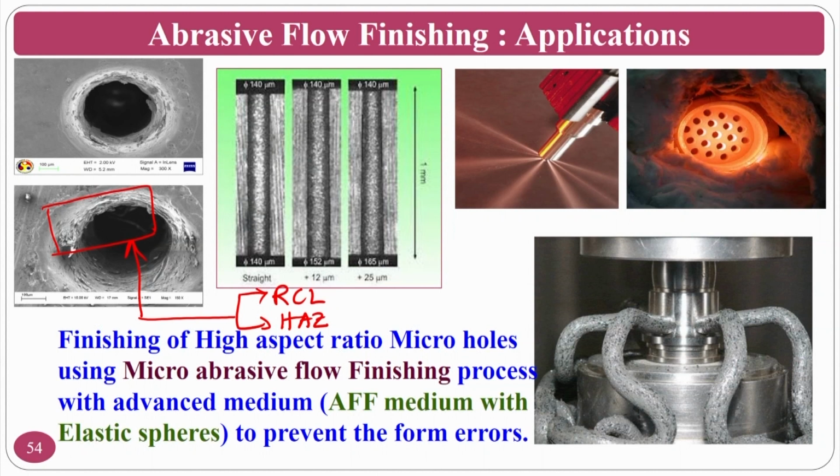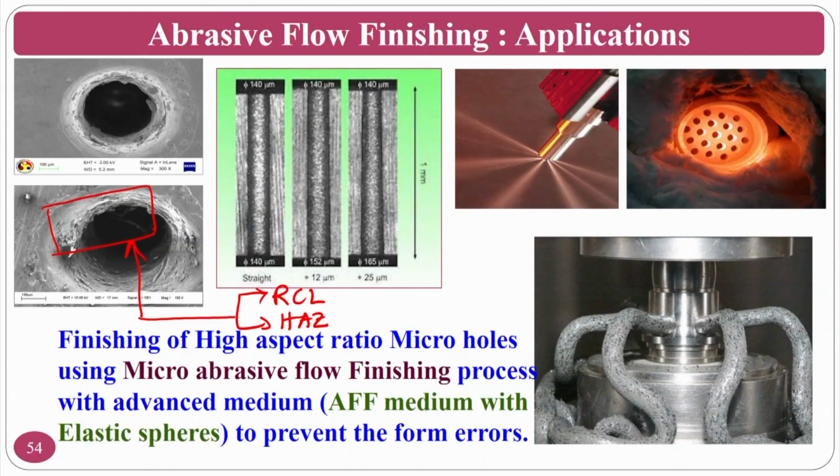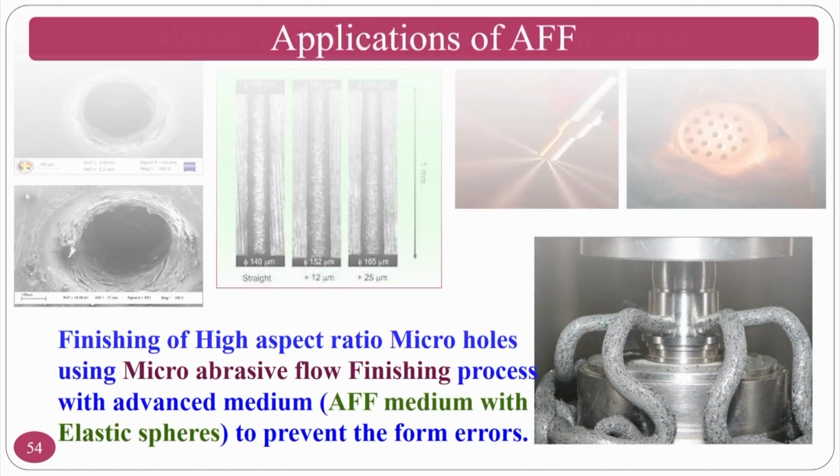These recast layers have to be removed, otherwise whenever these come into practical applications, these particles may go away and may cause us a lot of problems. This may be in biomedical application, in fuel injector applications, or many other applications like filters. Okay. So, you have to take care of these particular surfaces, so that you can remove this recast layer and partially the heat affected zone, so that the good parent surface will be exposed to the practical application.